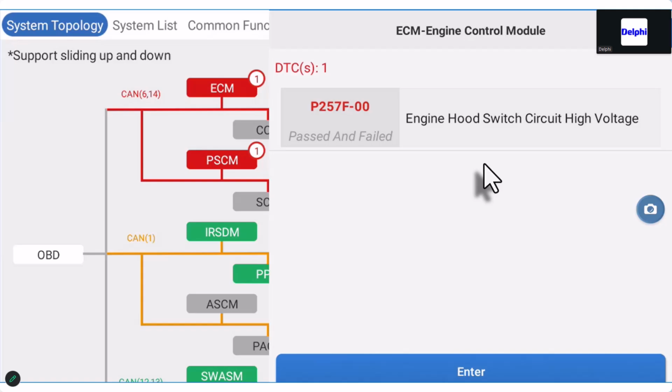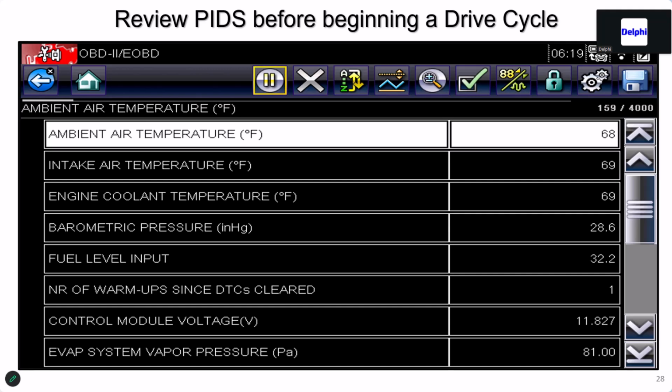After he replaced it, the O2 heater ran right away. The VVT ran right away. We did some other work on it. Got the cat to run. And over the weekend, last weekend, he got the O2 to run. It wasn't just this, but this was one of the blockers. And then there were some other issues, mechanical issues, reporting issues that we got fixed. And I'm going to do those in a later case study in one of the other classes. So keep that in mind.